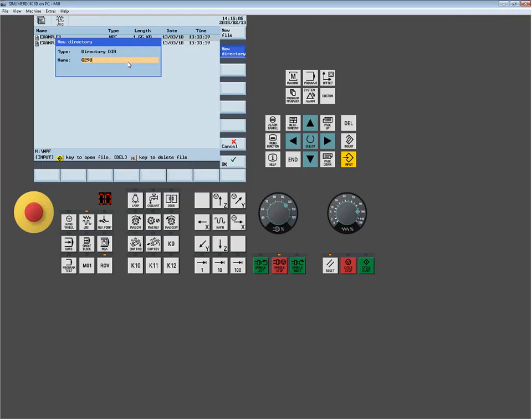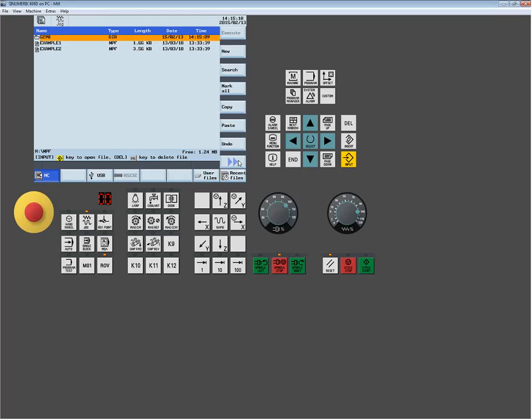So in this example, I have a 3/4 inch end mill that's going to do my primary rough machining around my peripheral. Then we have a 3/8 end mill to do the helical hole in the center. And then we're going to use a center drill, which is 3/8, and a quarter inch drill to drill the holes. So if I select milling, simply type the tool number. Now this would probably be one of the first things you're going to see that's a blaring difference between the 808 and some of our more advanced controls like the 828 and the 840. And that's the fact that in the 808, you only can assign tool numbers as names.